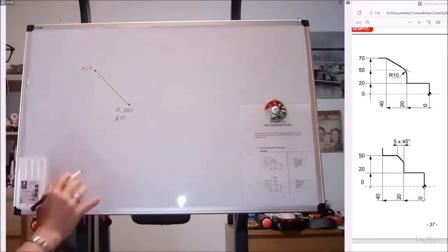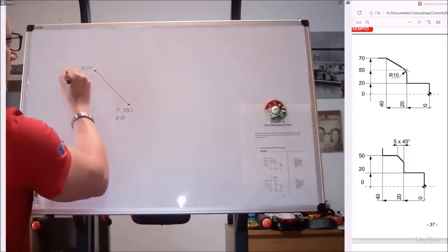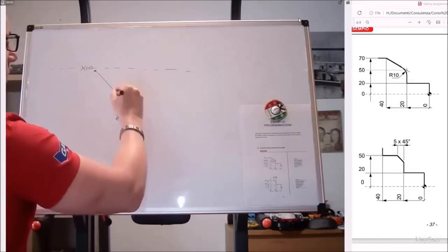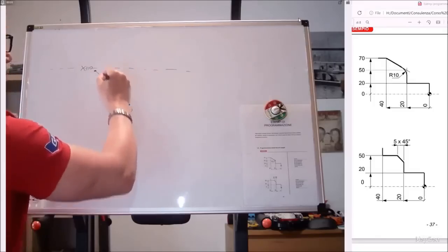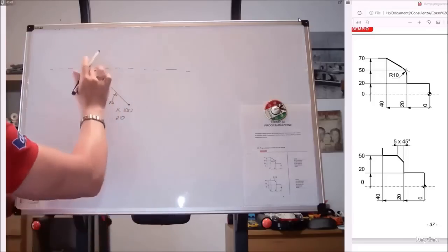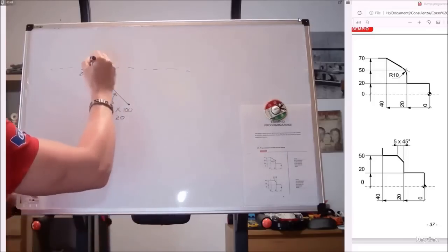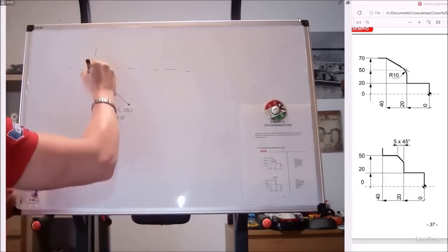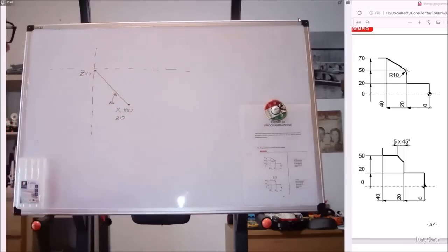The machine starts at 45 degrees and will stop at x110, regardless of the arrival z, meaning it will have this as a barrier and will be determined by the travel angle and the x where I tell it to stop. Or I can tell it the angle and z minus 10, so it will have this as a barrier in addition to the travel angle.